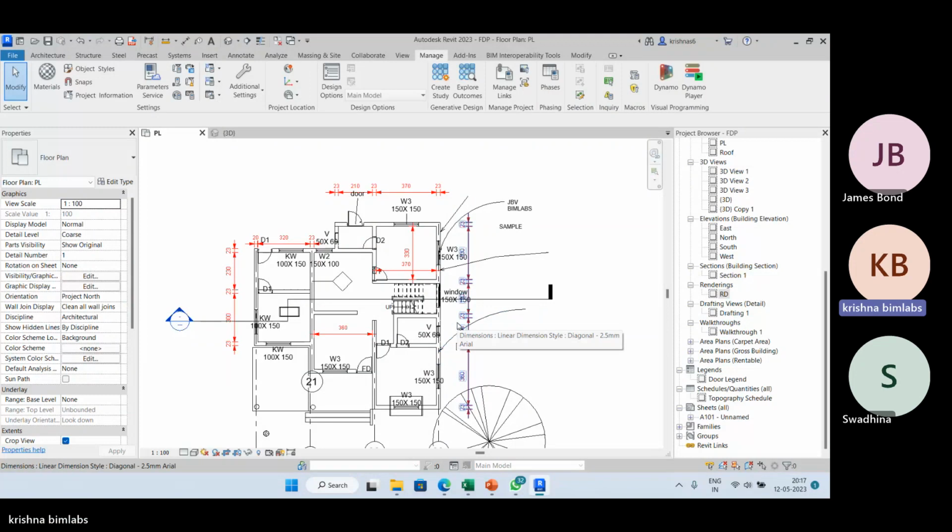Okay. And in this one, the rating or the energy analysis is done by the ASHRAE rating, the American Society of Heating, Refrigerating and Air-Conditioning Engineers. Their ratings or their study values will be given here for this particular model, and we'll just compare. If there are any suggestions, we can make them. And here Revit plus Insight will do the energy analysis. I'll show how to do the energy analysis, which mainly depends on the R values and U values.